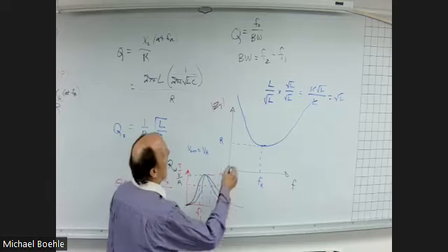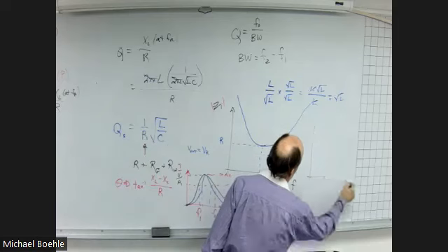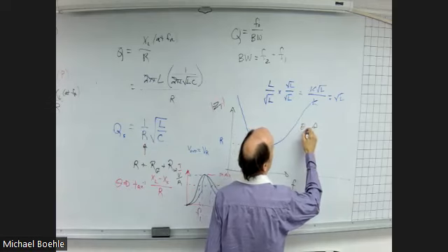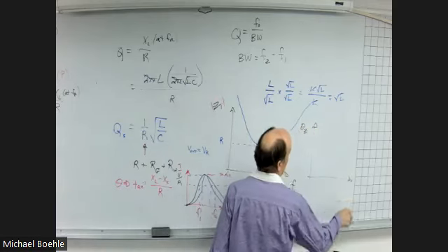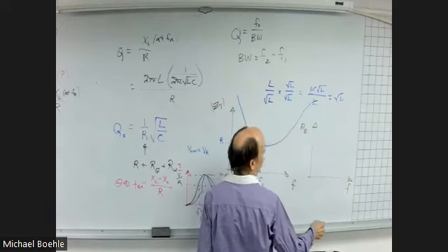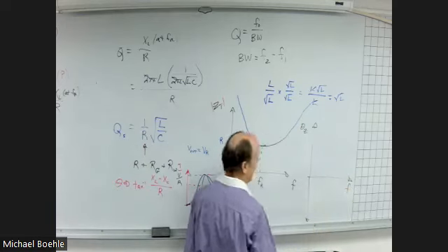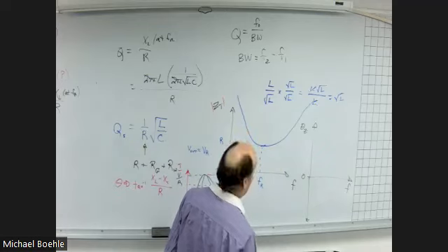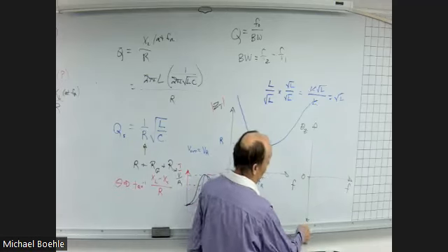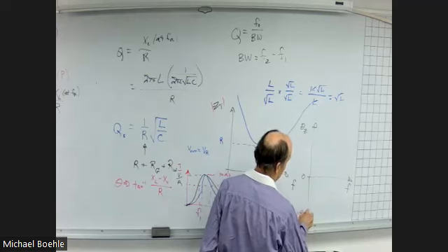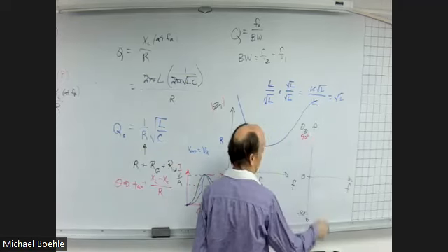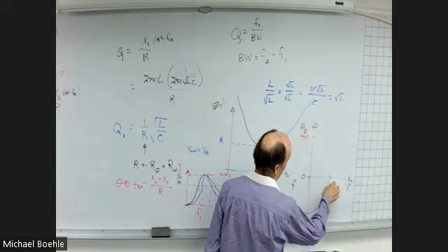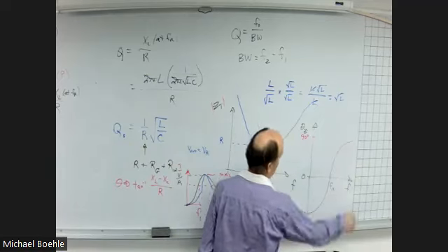So if we were to look at the, I can do a graph, I guess. Phase shift, right? And this is the angle of the impedance versus frequency. Actually, I need there we go. Because I have 0 right here, right? There's 0. So the angle of the impedance starts off negative at a very low frequency. It would be minus 90. And eventually it would get to 90, theoretically. It's going to start there. Pass through 0 at the resonant frequency. And go from there.